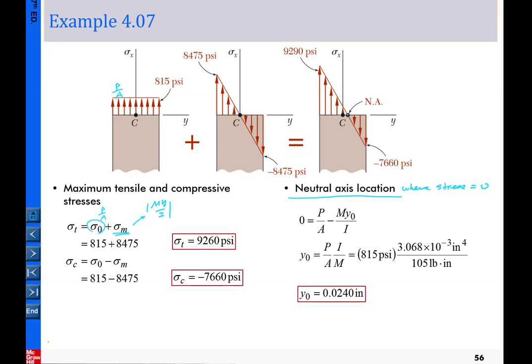We know for this case, the stress equals P over A, and for this case, material in this portion is in tension, and material in the other portion is in compression. And the magnitude of the stress for this case is My over I here. Again, this is the magnitude, and y is the distance. For example, here, if we're interested in this point, y simply is the distance between where we are interested and the centroid of that cross section. That is what we define as y in our formula here. Okay, so keep this in mind.